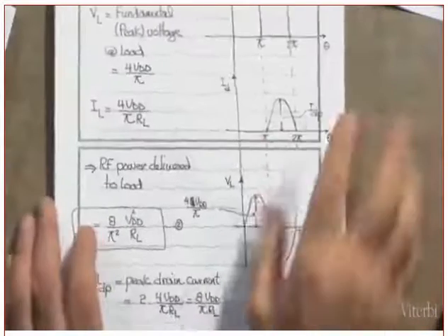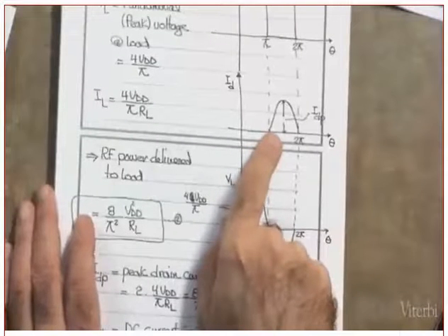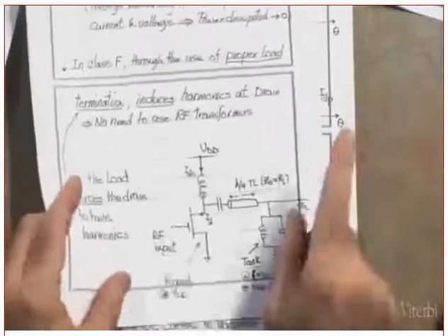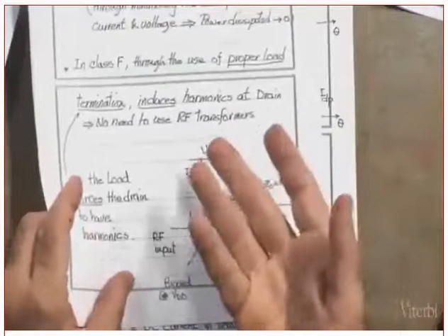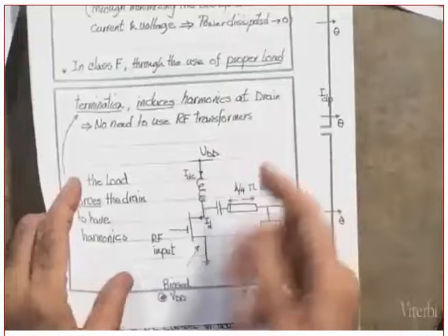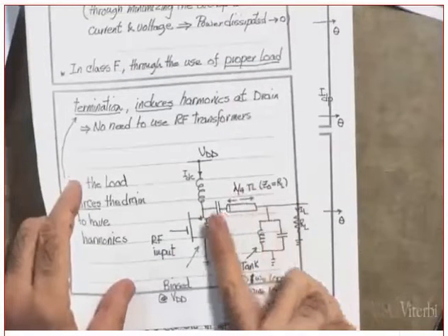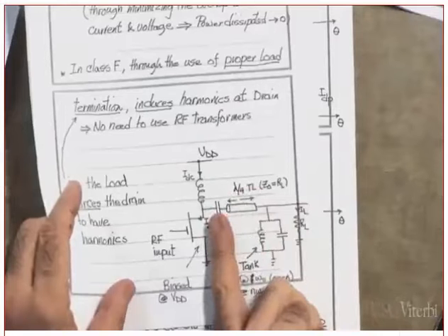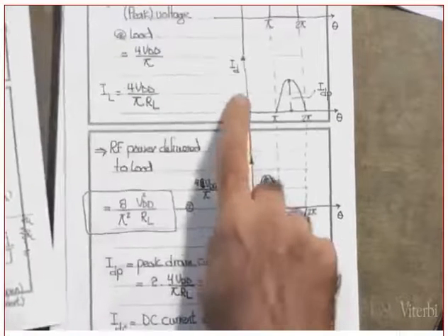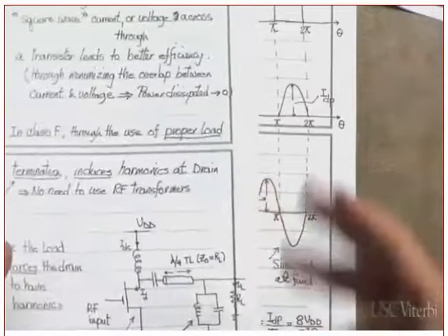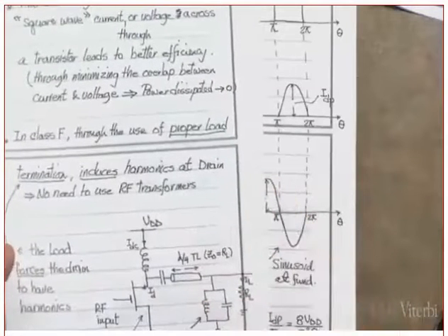Okay, but I need you, first of all, to explain this one to me. Why is this one like this? Why is the load like this? Now, notice, by the way, all the even harmonics will go where? The current. Remember, the even harmonics in here will be shifted to 0. So this current, which is the drain current, will be only the sum of the harmonics. Did you get my point or not?